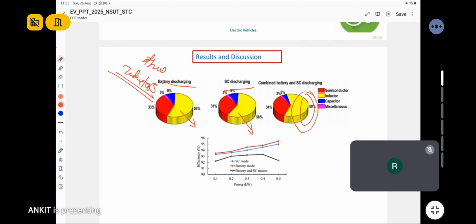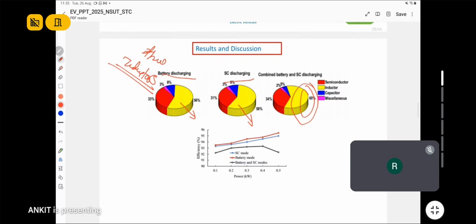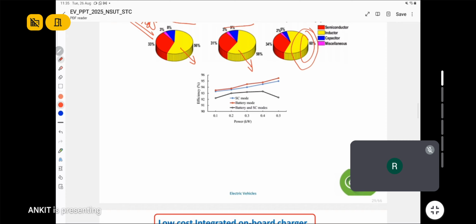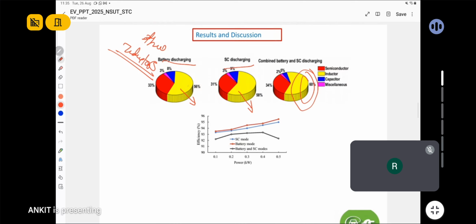because the inductor has a high equivalent series resistance, which is its parasitic resistance. So we should take care in the design of the inductor so that the losses can be minimized. It means we need quality copper material and minimum core losses, because not only copper loss of the inductor is there, its core loss is also there.